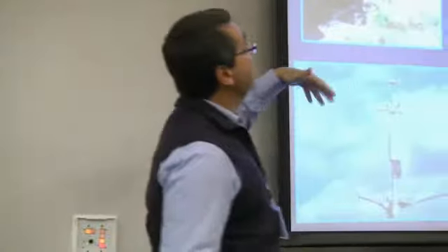You can see a picture of the surface renewal and eddy covariance tower in these two pictures, and you can see the sonic anemometer and different sensors that at the end will give you the evapotranspiration as a residual of the energy balance. At the same time, when we do this, we also measure the soil moisture, and we measure the plant water status in order to make sure we're measuring something that is unlimited.